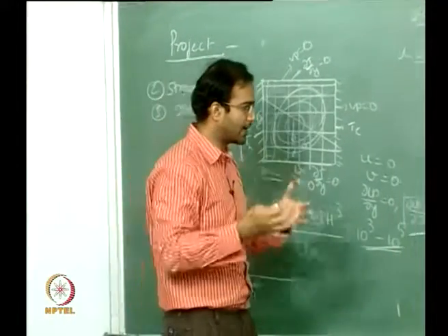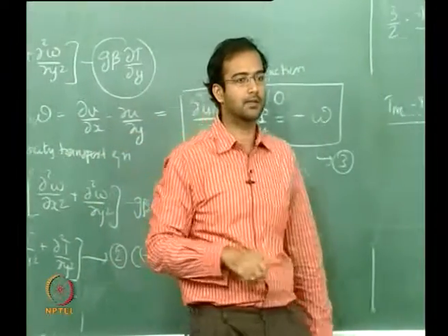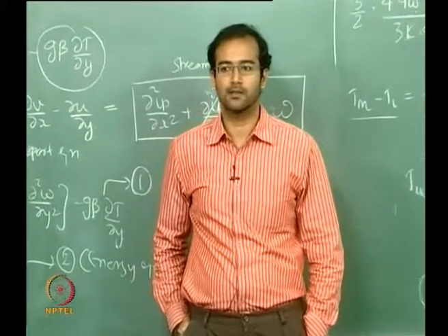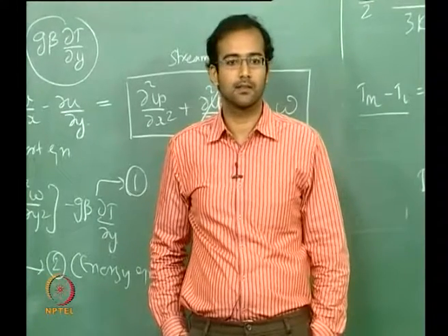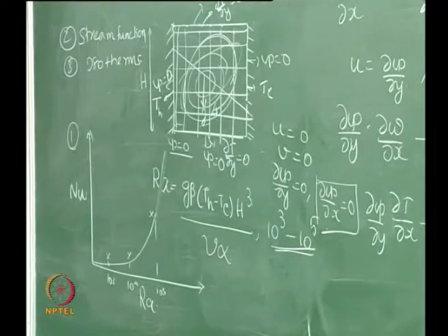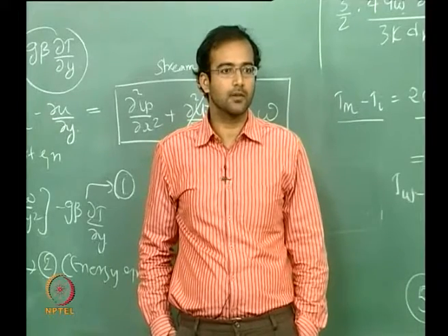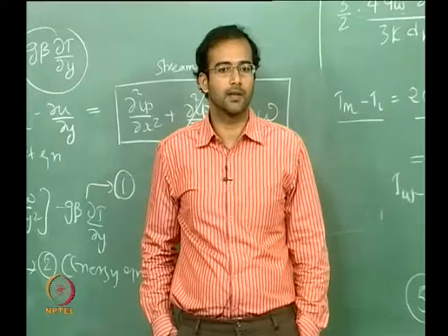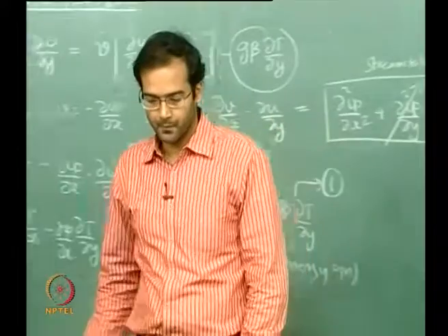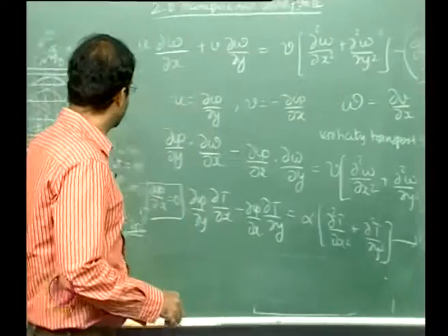So this gives you a very good idea practically how you solve the Navier-Stokes equation in the two-dimensional case. There you have the advantage of reducing it in terms of stream function and vorticity, and you can get a direct solution through finite differences, and I think that will hopefully give you a better appreciation of the subject when you go to the research level. In research we need not do everything by similarity solution, so that gives you also an exposure to using some numerical methods.